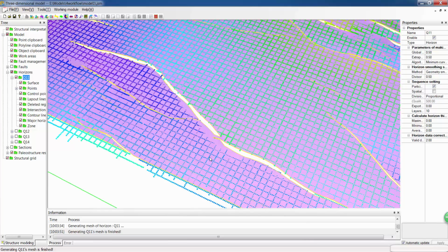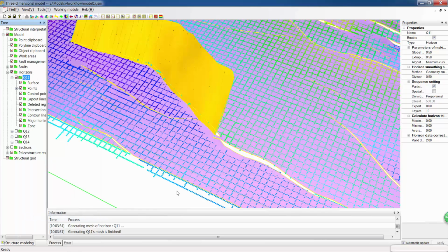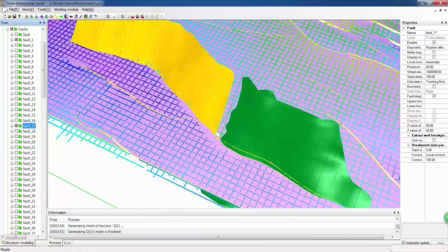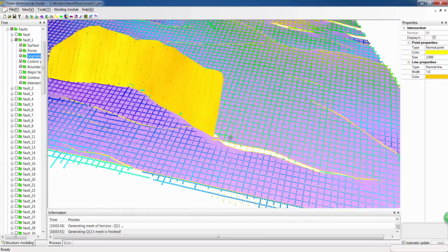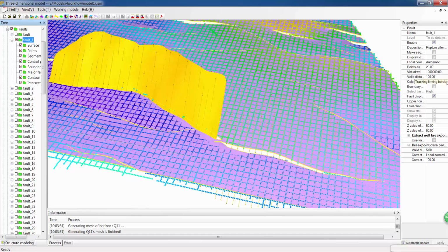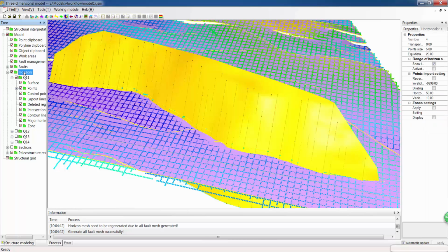As we can see, there is an issue. The two faults were incorrectly separated. We can edit them by selecting both individual faults to merge them into one. And now we will use a different methodology of automatically generating the new fault boundary for our merged fault. We next generate all of the full horizon surfaces. It usually takes 18 seconds.